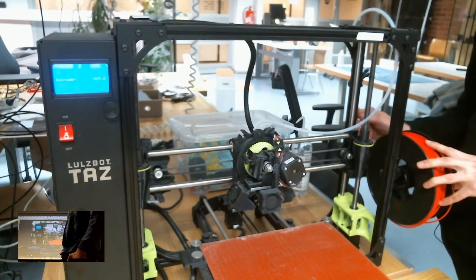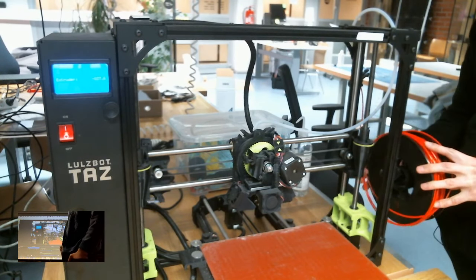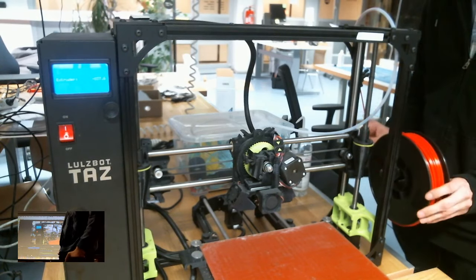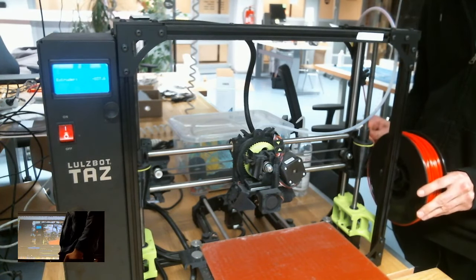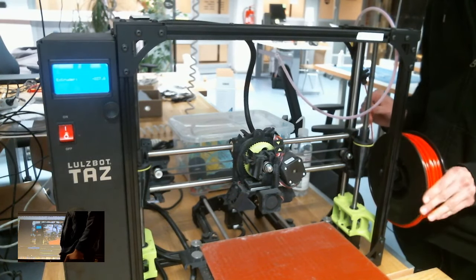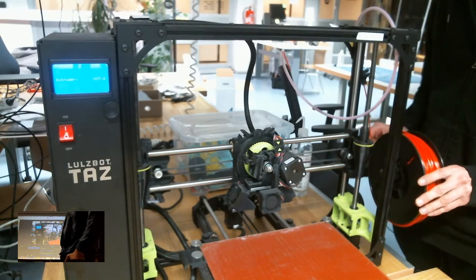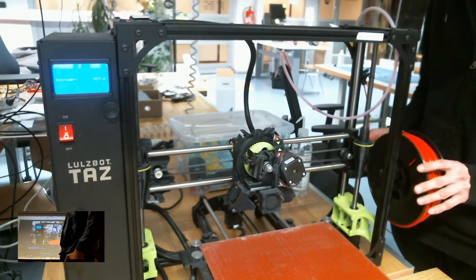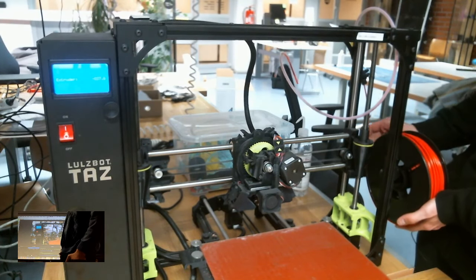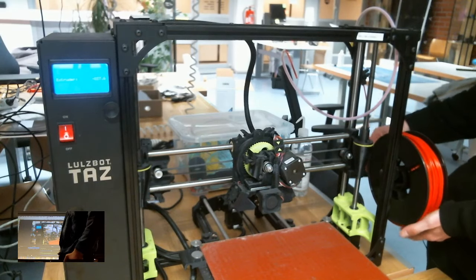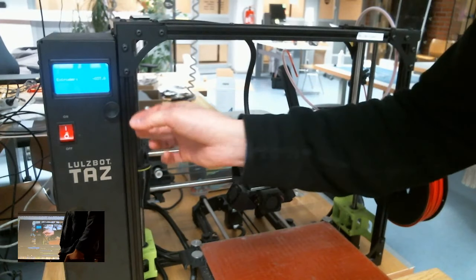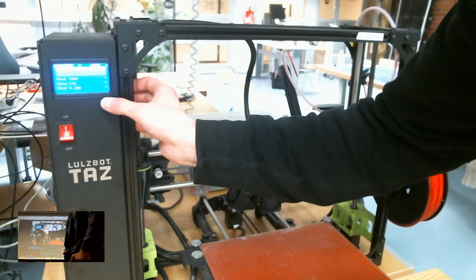So in case there's no filament and loading filament is the first step that you do, you need to remember to heat up the nozzle. Some printers will have a separate function, load filament, and they're going to try to do that automatically, but yeah, good practice is to make sure. So if there's no such function, then always remember to go and heat it up to 220 or whatever the material requires.